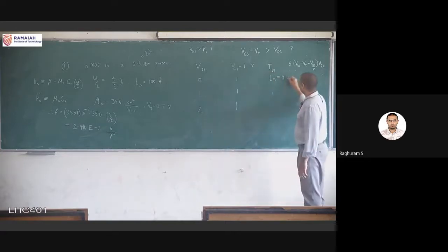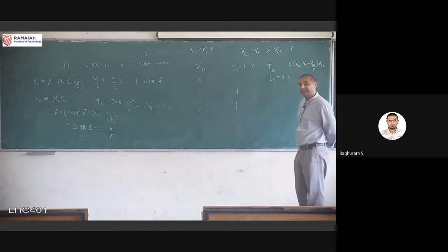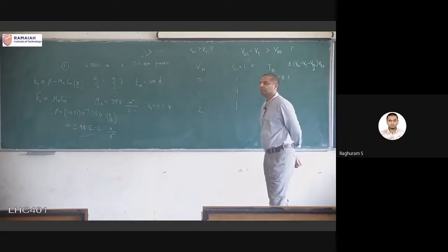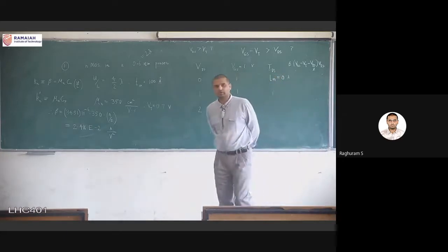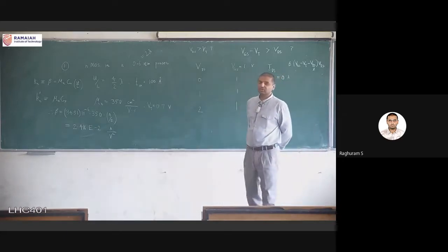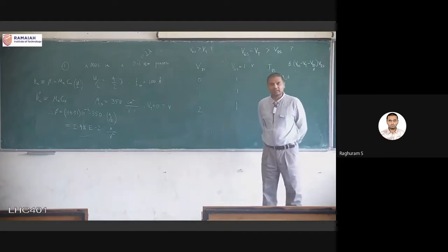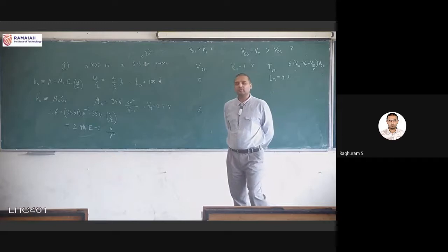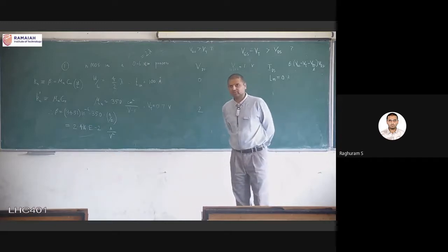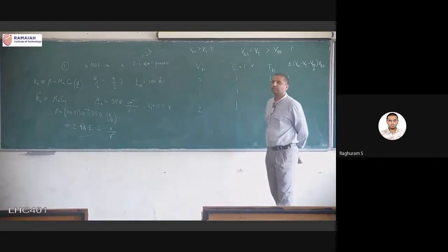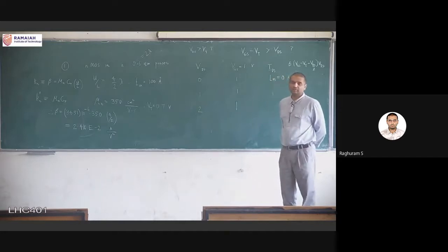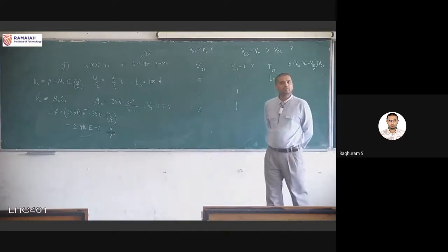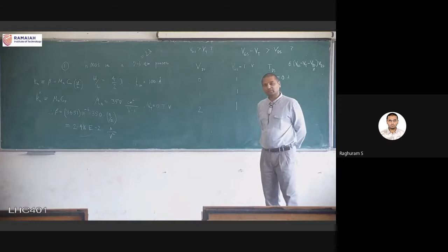In this course, we don't care about the calculation. We know that there are certain currents flowing all the time called leakage currents, because we have discussed all these non-ideal effects. There is subthreshold conduction also, but we are not going to calculate all those currents. If we find out that the transistor is off, current equals 0. If VDS equals 0, then also current equals 0.